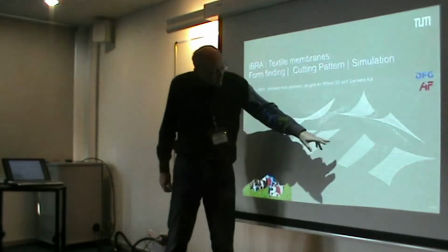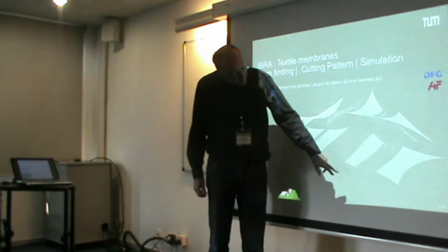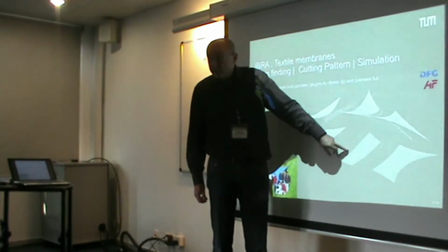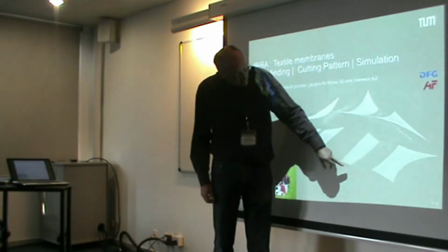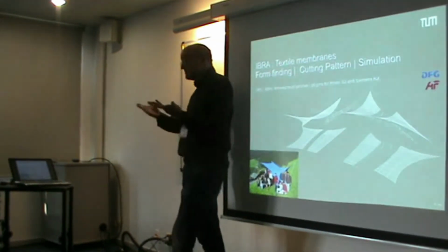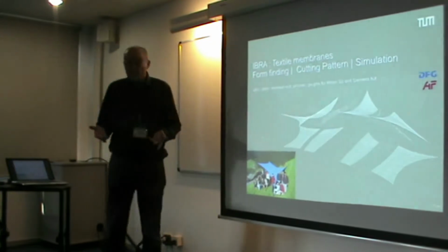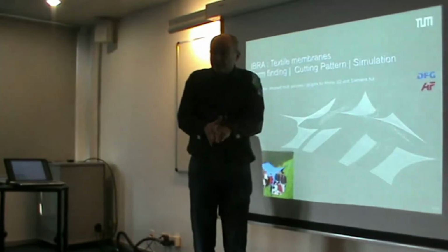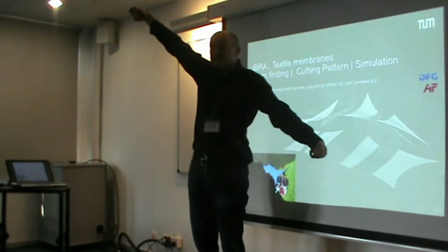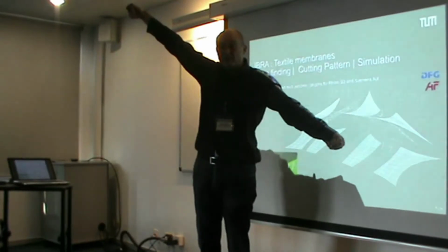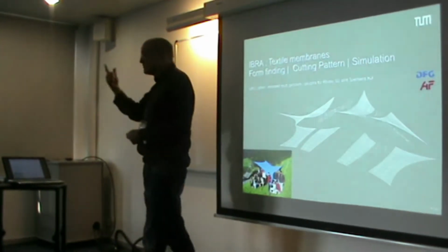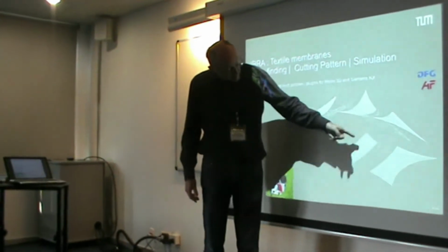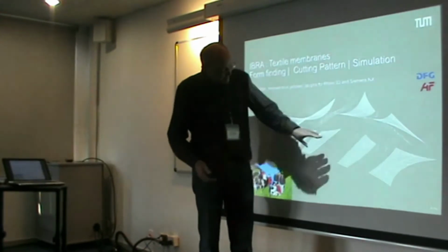So what you see here are the control points in a CAD environment. Here are these control points, and you see we just have trimmed those patches, which you don't see, to the remaining cutting pattern. And that's again an optimization problem, another optimization problem, where to put these cutting lines such that after putting them together and putting them into space, the intended shape and stresses just appear. So in that sense, we have two types of trimming problems. This, I would say, is the mechanical trimming operation, where we really have to look for the cutting pattern. That's what you see here.